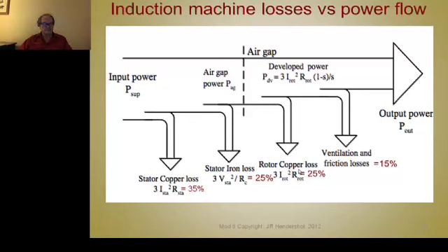This is for an AC induction motor, by the way. And then your windage and ventilation and friction losses. See, when you air cool a motor, you blow air through it. That causes additional friction as well.